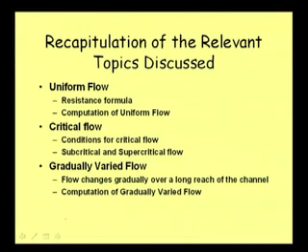And then of course we have studied gradually varied flow, how the flow changes gradually over a long channel reach. Rapidly varied flow is also a phenomenon where the flow depth changes, and gradually varied flow is also a phenomenon where the flow depth changes. So in gradually varied flow, the flow depth changes slowly, or rather gradually, within a long reach of the channel.